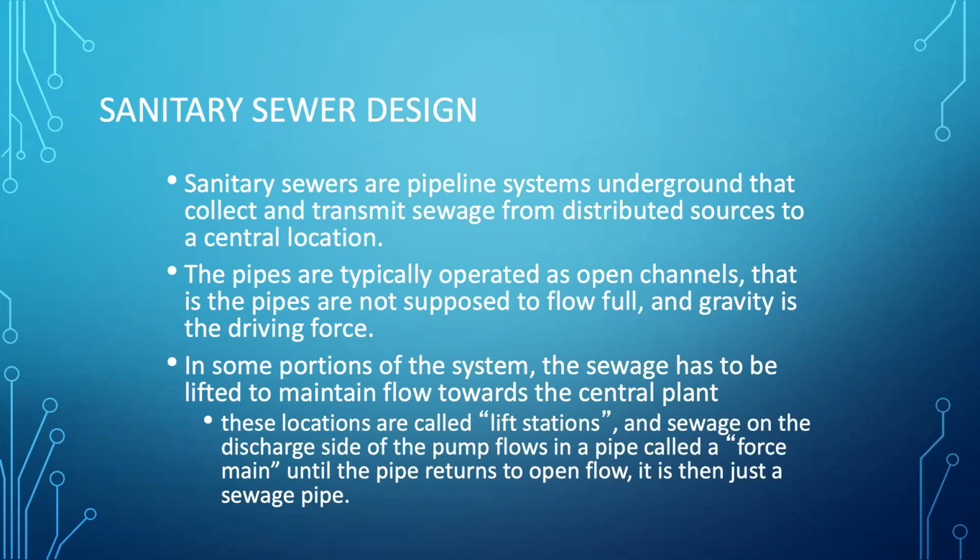Keeping in mind that statement, visualize for a moment what would happen if a sanitary sewer pipe did actually surcharge. That means that the water surface elevation, if it could, would want to lie above the top of the pipe. That wouldn't bode very well if you happen to be in the vicinity of where that sewage came flying up out of the ground. And that happens in the real world from time to time. And it's a good form of job security for hydraulic engineers if you're into it.